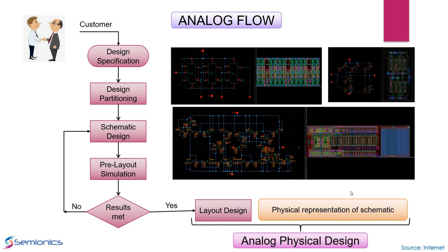So what happens in layout design? Assume that a designer has done the schematic of this AND gate. A layout engineer does the physical implementation of the gate over here. Using this, they build the next hierarchical design. Assume that this is an analog design, which the schematic designer has done. There are lots and lots of layout design techniques and concepts based on which a layout engineer does the physical implementation. Now here is an op-amp which has a current mirror, a differential pair, a biasing circuit, and there are resistors and caps, whatever.